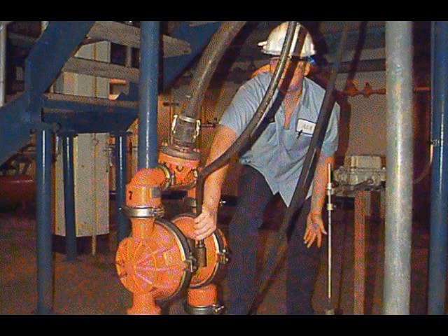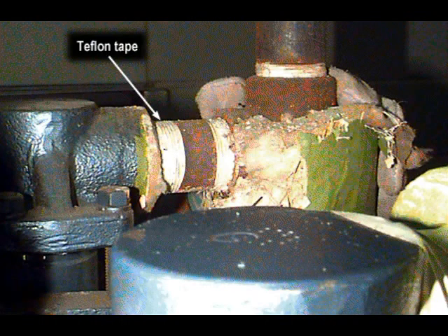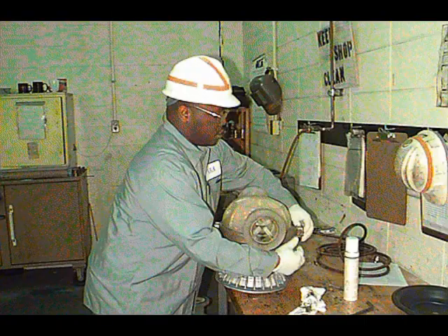The operator will be responsible for cleaning and tightening valves and fittings. At least every 6 months, everything including the diaphragm should be checked, cleaned, and replaced if necessary. Remove any old Teflon tape used to help seal valves or fittings that are being replaced. Apply new tape and then finger tighten. Do not use wrenches to tighten plastic fittings. Forcing a plastic fitting can damage it.